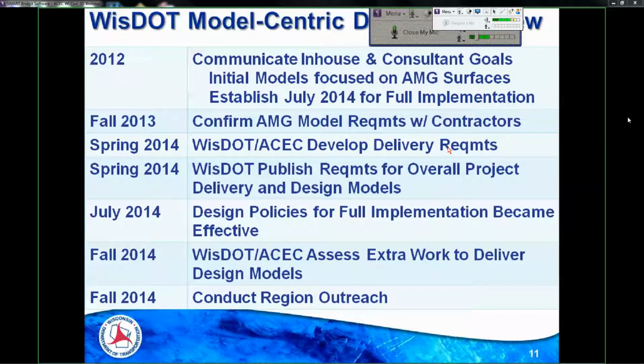And that's where the longitudinal break lines really elevated their importance in the priority of our deliveries. Because we realized that these contractors that don't want to use our models directly, we can still give them things that are of value, and they're telling us the longitudinal break lines. They can build the extra detail into their surface models if they only have those break lines. They can't do it when we just give them the surfaces.